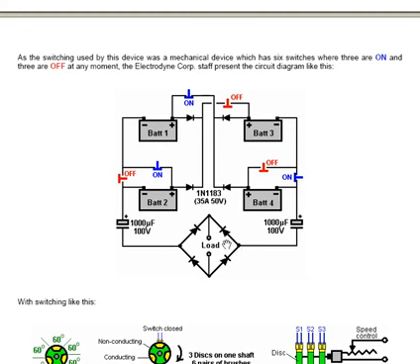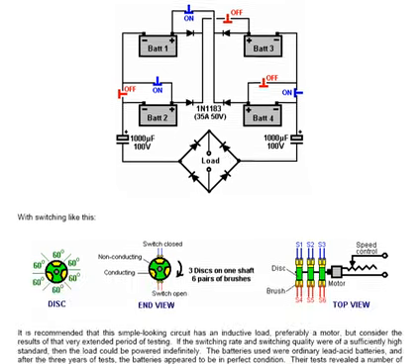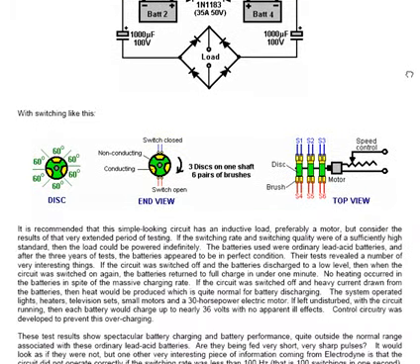The switching arrangement that they used was like this. They had a rotating disc, separated into 60-degree sections, and the middle 3 of those sections is faced in conducting copper, and that conducting copper is used to short between pairs of isolated switches which are alternately on and off due to the insulating green shown area.